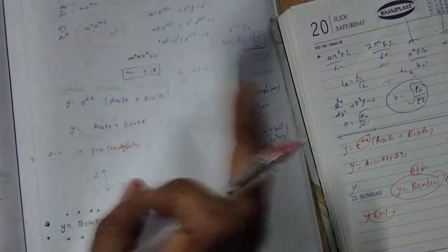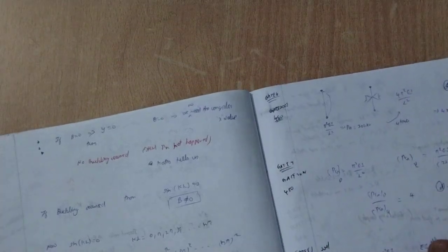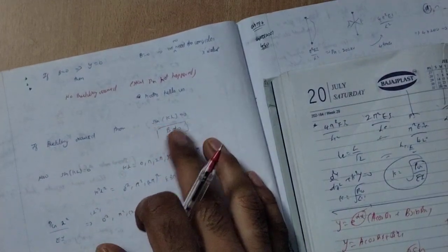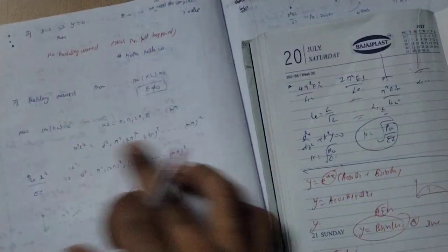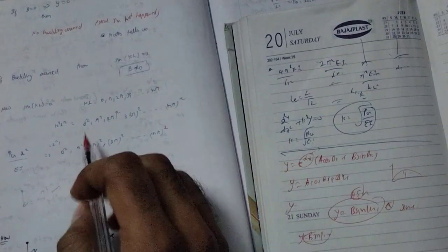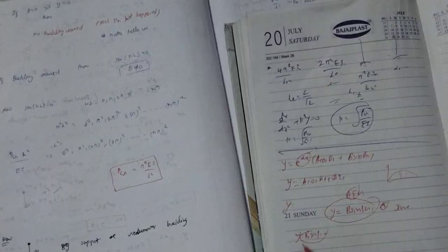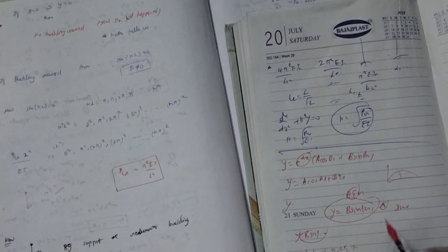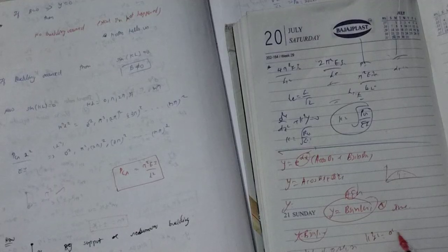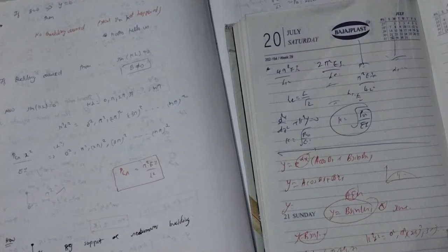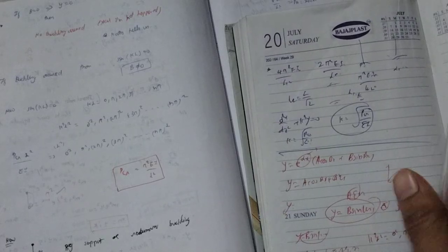This is the equation. If buckling has occurred, then sin kL should not equal 0 for B nonzero, and this kind of thing occurs at buckling. So kL equals 0, pi, 2 pi, 3 pi, up to n pi, so k square L square equals pi square, 2 pi whole square, 3 pi whole square, n pi whole square.